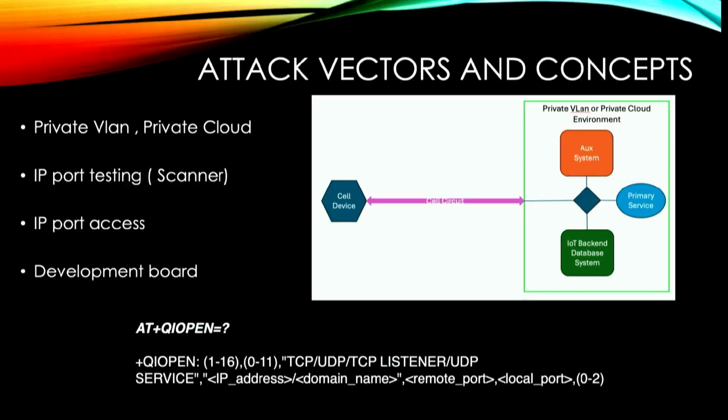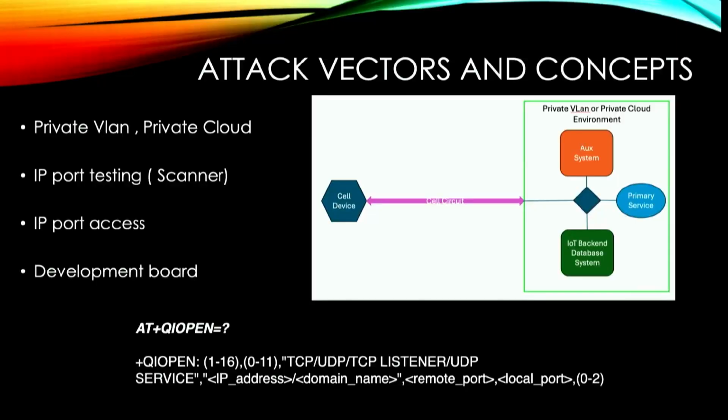This device actually uses USB net to set up a connection for the underlying operating system to be able to pass data. It's just none of it's encrypted, so we're able to see it all. But it's network actual data. So you could easily do that, basically turn a development board into a network interface card using all this data, and then I have full access via the network. That is for devices that pass large amounts of data and follow the USB net setup function.